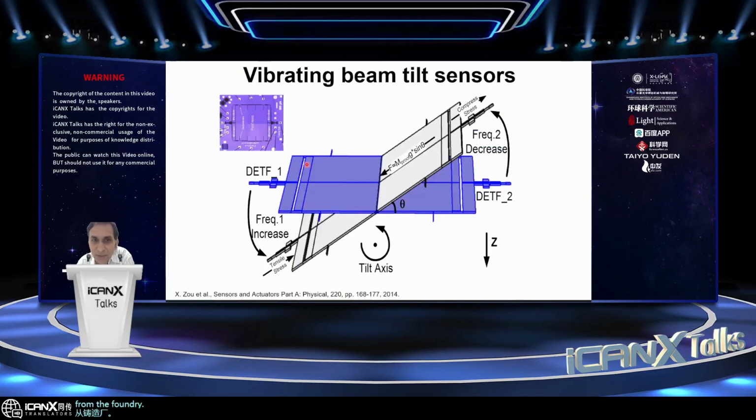And so this is work that Shudong was involved in. And the first sorts of tests that he did, and there's a die photo inset, and the first set of tests was to mount this on a tilt platform and to record changes in the natural frequencies of the tuning forks connected to either side of the mass. So the idea here is that the two tuning fork strain gauges are connected up to this mass through, for example, a leverage scheme.